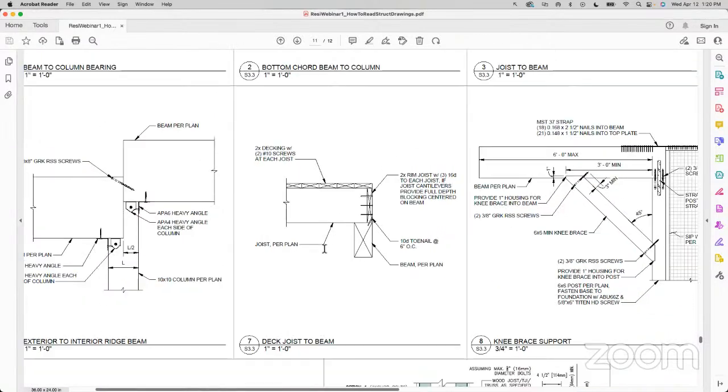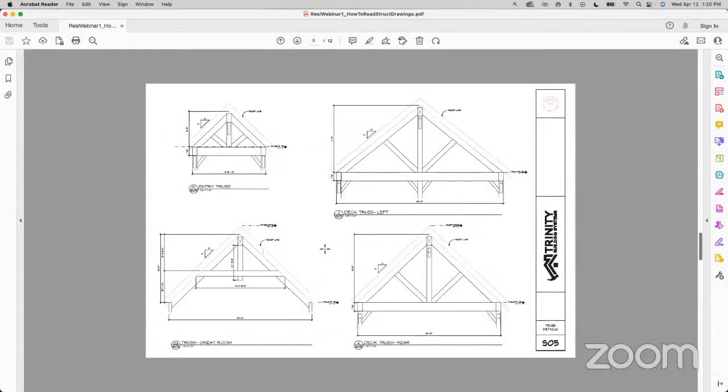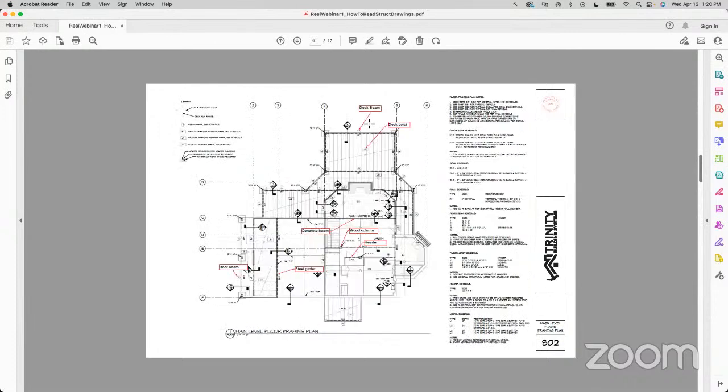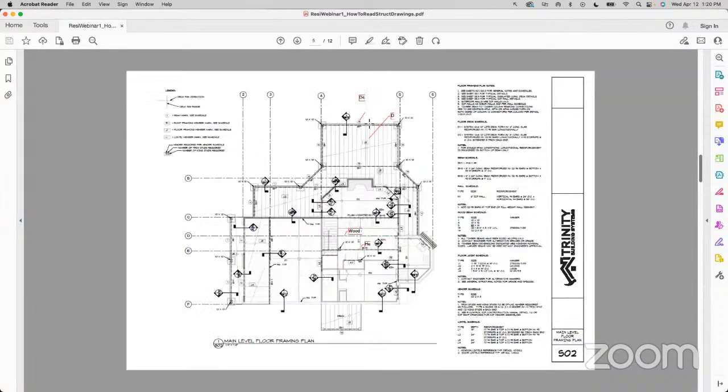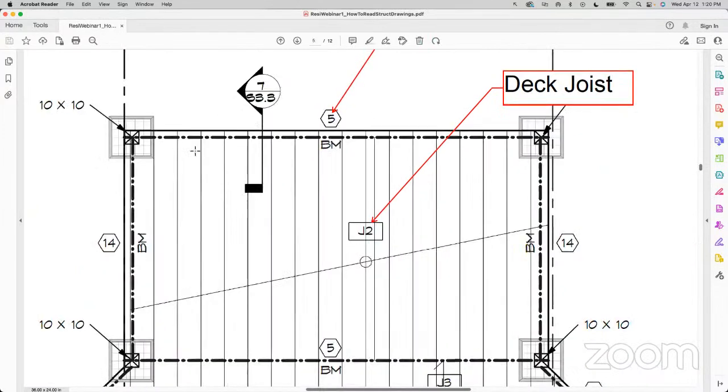All right. So what we're doing, we found our 7.75 inch bearing length. But what we're going to do is find the actual controlling one. And I'm going to make an assumption here for the sake of showing you something that ClearCalcs can do. So what we did, we found the bearing length on the top. And now we want to find the bearing length on the bottom of our joist.